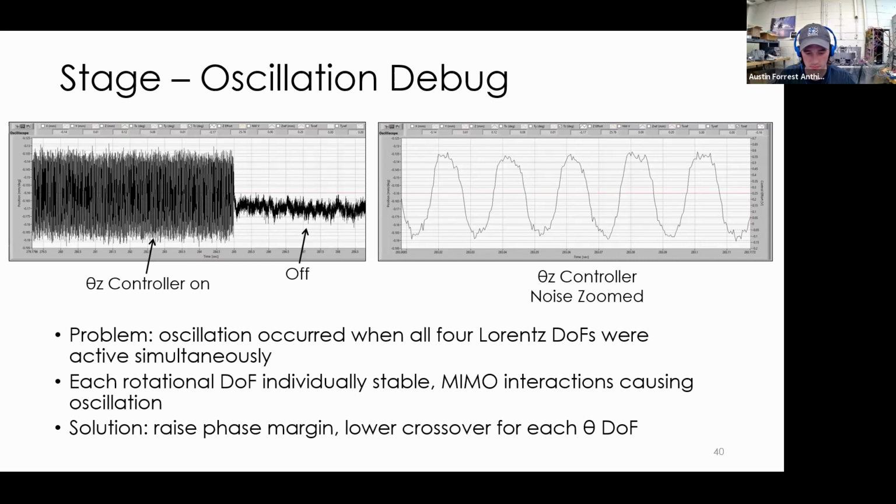Also there are nonlinearities, like in the hub actuator, and dynamics, as you might have different breakpoint frequencies on different actuators, so the forces you think you're making aren't dynamically equal. There's a lot of places where this simple idea falls apart, but it gets used a lot for maglev stuff. This is really one of the standard solutions, and we've used it in a lot of different contexts, this idea of decoupling.